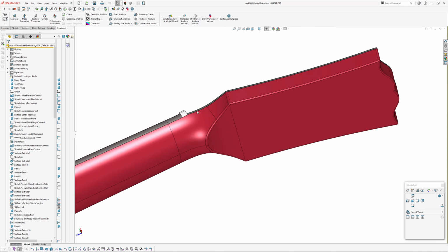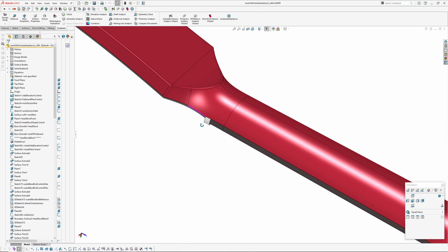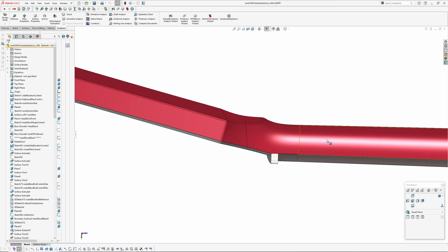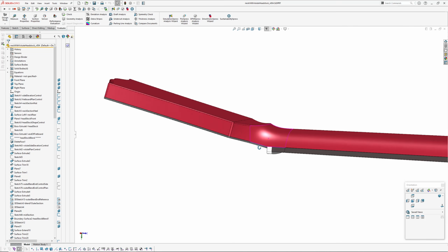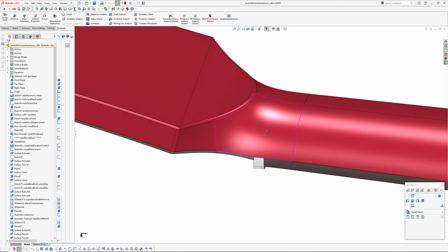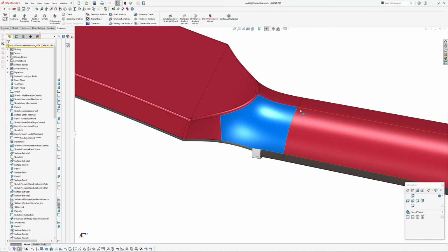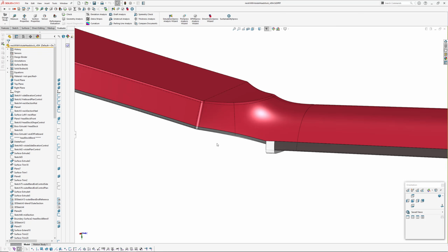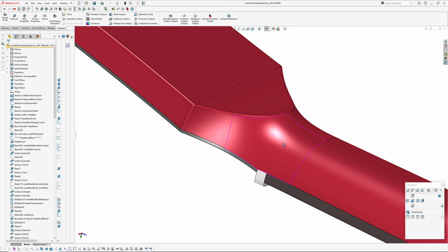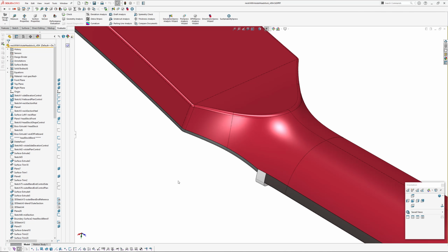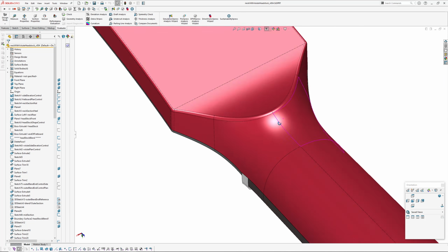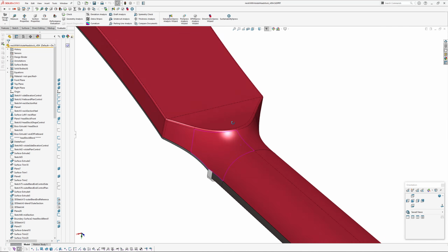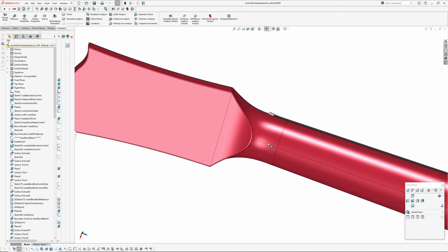So as I said at the beginning, I think there's enough here that you'll be able to follow a similar patch layout if you're working on an asymmetric headstock, or a headstock that runs planar or parallel to the fretboard, like a Stratocaster or Super Strat. So basically, build this one big surface first, trimming back a little bit of it so you can add a second four-sided patch in. That means we're not trying to make five-sided surfaces. We've avoided using the fill surface, so we've done this just with standard surfacing tools. Should be fairly robust. So I'm going to wrap this up there.